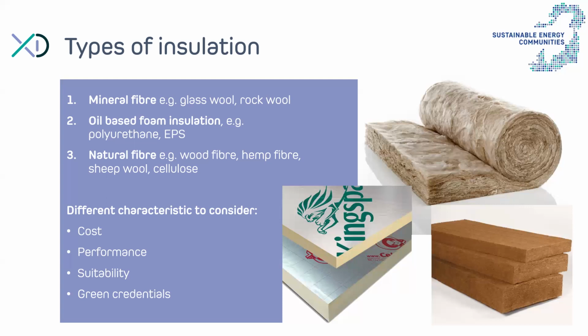So there is increasing evidence and awareness that insulation materials do require energy for their manufacturing, and they have what we call embodied energy, and with that a carbon content. So we need to balance the level of insulation that's achieved and the reduction in heat loss, but also take into account the fact that these contain energy or carbon that needs to be offset. Typically, the balance is positive in that you recover the energy that's built into the material through energy conservation over a period of maybe 2-3 years in typical situations. But from the point of view of environmental impact, we would favor natural fiber materials wherever possible and, budget allowing, they can be a really good option.